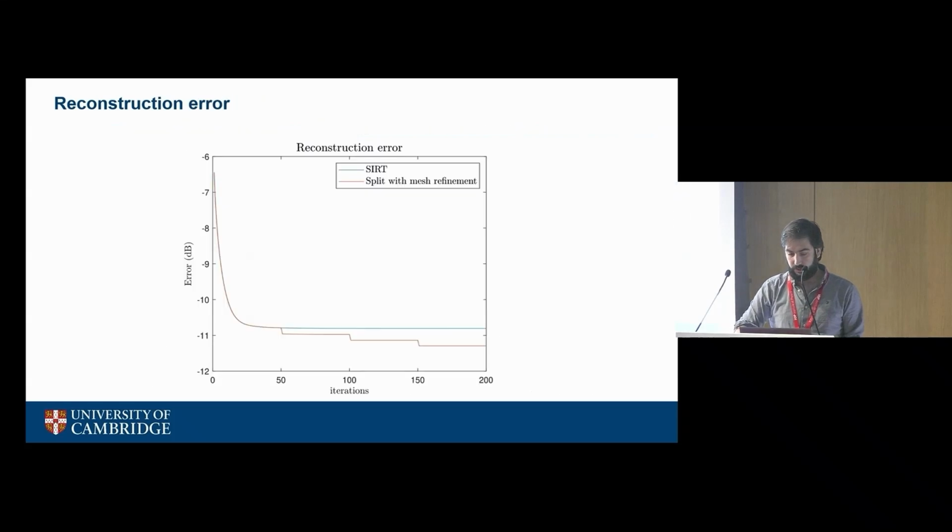And so, okay, I won't get into this, but you can see that the error versus your ground truth goes the same, and then you can refine the mesh, refine the mesh, refine the mesh. So you can capture all these small things that are in your data, which a voxel grid may limit, while still keeping the area that is not interesting at low element counts. And again, this can only be done with iterative reconstruction because your standard algorithm doesn't really work on non-voxel meshes.